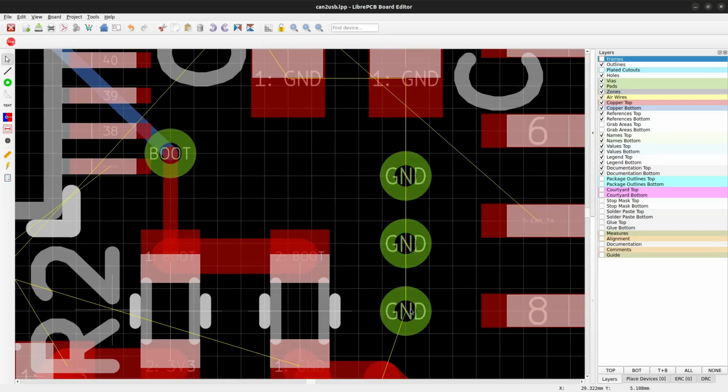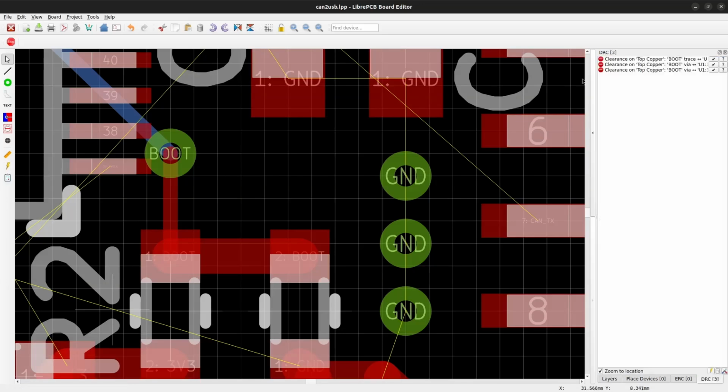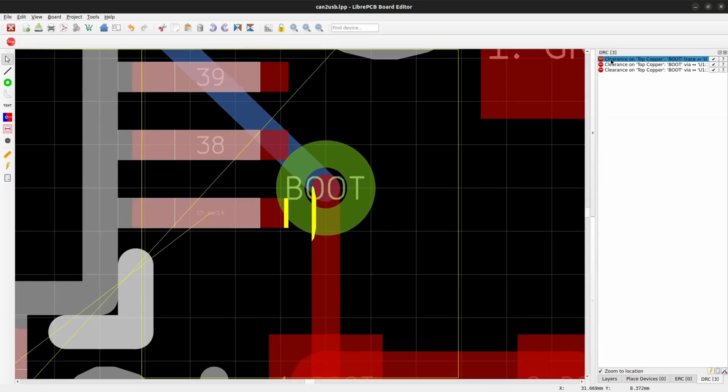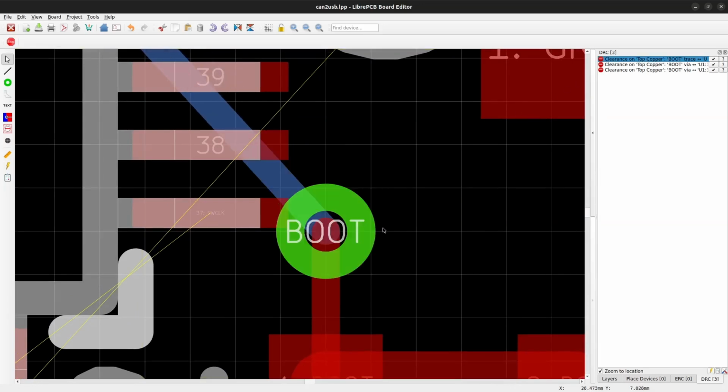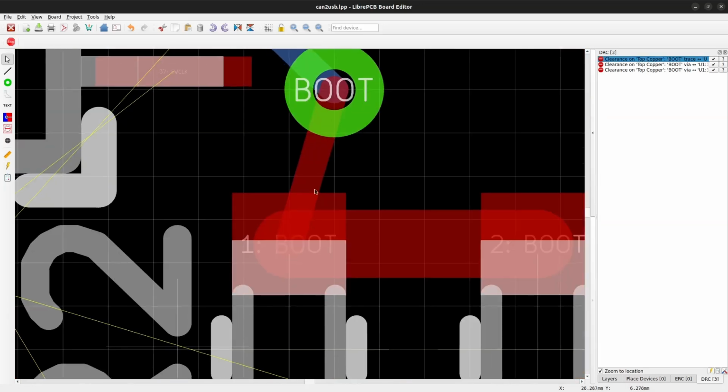Whenever you're unsure if there's enough clearance between traces or pads, you can trigger a quick check. This is basically the DRC but runs only the most important checks to get much faster feedback. Mainly copper widths and clearances are checked, so this tool is especially handy while drawing traces.